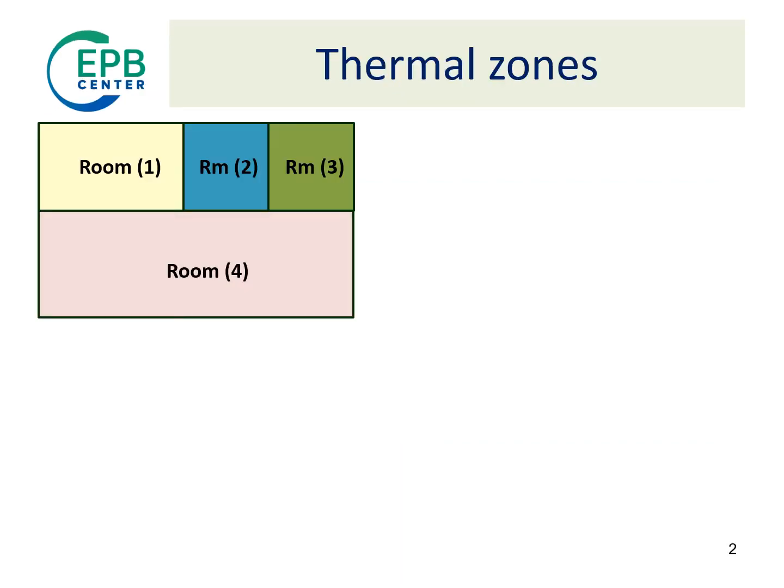Most buildings do not have the same conditions evenly distributed among the building. Therefore, we need to split up the building into parts. For each part, the energy ins and outs are calculated and in the end assembled. This dividing is called zoning. Zoning has two basic layers, the thermal zones and the service areas.